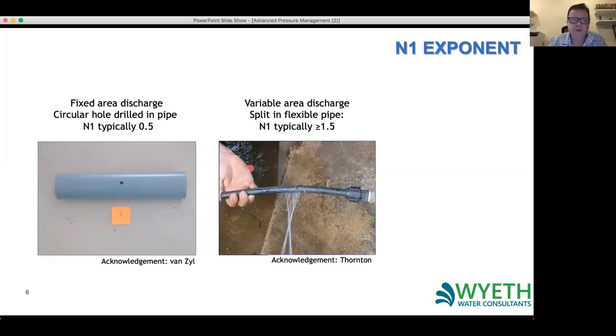But that formula is actually based on analysis that's done in labs whereby leak holes are similar to this. They drill holes in pipes and they force water under different pressures through that hole in the pipe to work out the volume going through it.